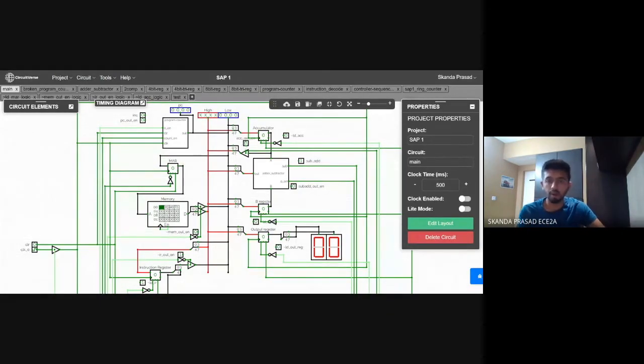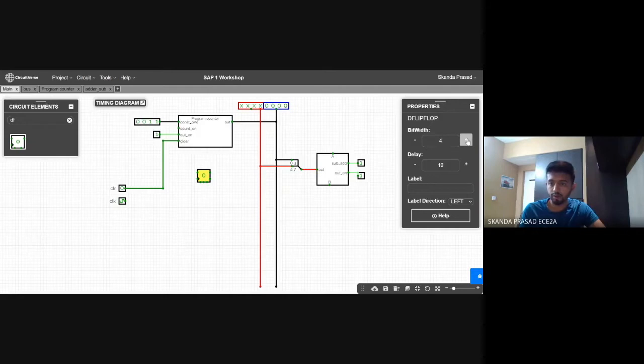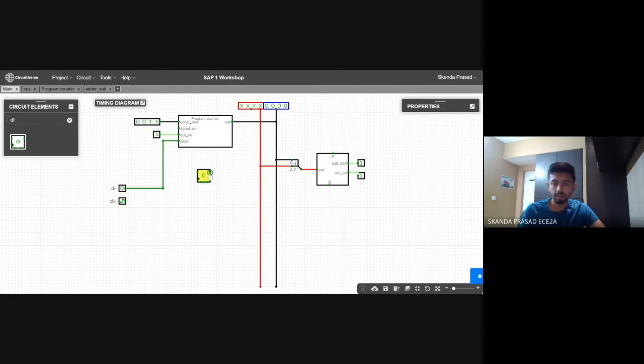So that memory can do a read operation. So that makes it clear that the output of the MAR and input are fixed, right? The output should go, that is, the output of the D flip-flop here. I'll just change the bit width also, make it 4 so that we don't forget it later. Okay, so its bit width is set to 4 and its output will go to the memory. I'll just leave it here because we'll be building the memory later. So we'll not be looking into that yet.